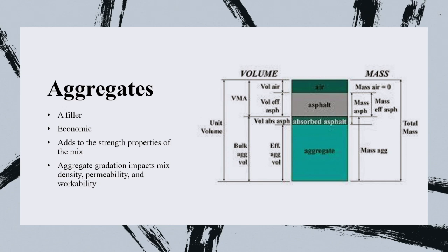Now, if the absorption capacity is 35%, right? The weight of the aggregate is several hundred kilograms. It represents like 75% of the weight of the mix. So it will literally absorb all the water. Then the cement will be a dry powder. You will not end up with a concrete. So before you do this, you have to submerge the aggregate and let it stay overnight in barrels full of water.